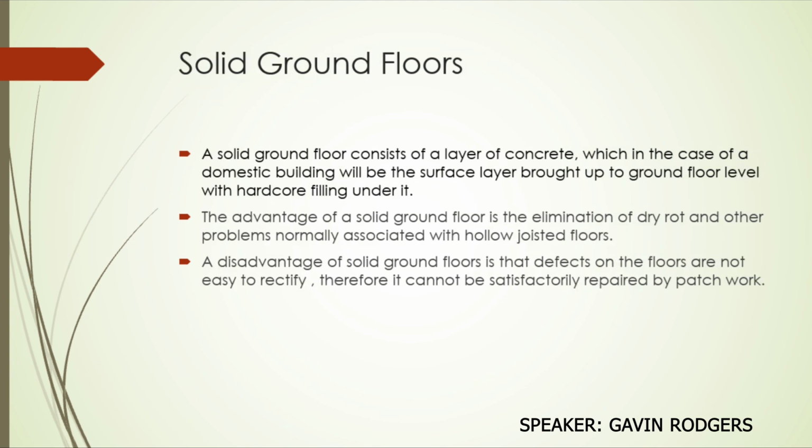Now we're going to look at solid ground floors and their components. A solid ground floor consists of a layer of concrete, which in the case of a domestic building would be the surface layer brought up to the ground floor level with a hard core filling under it. Later on we're going to see examples of this and pictures.